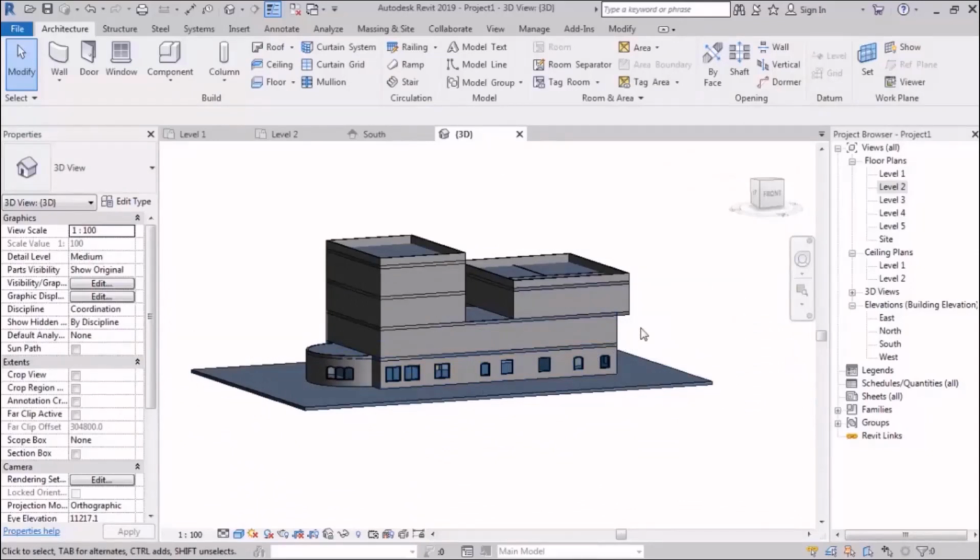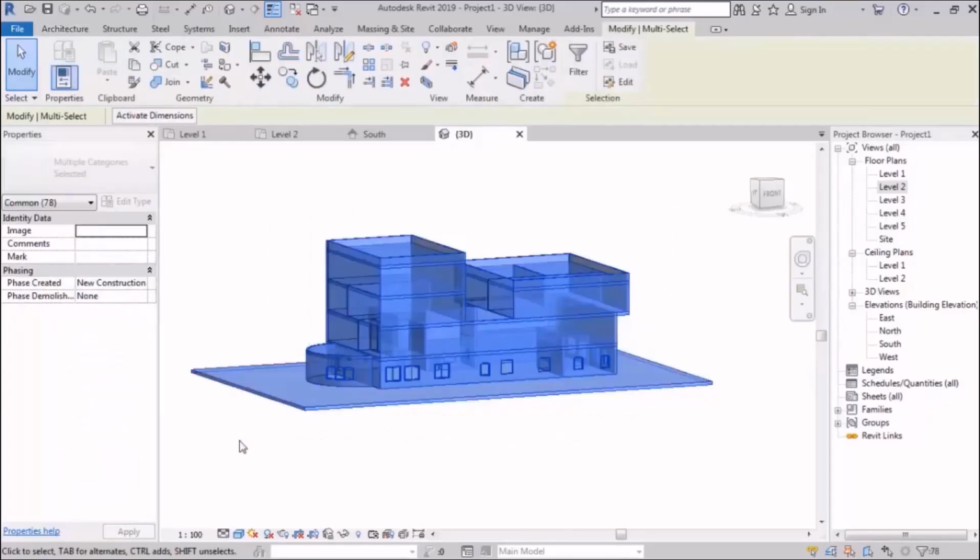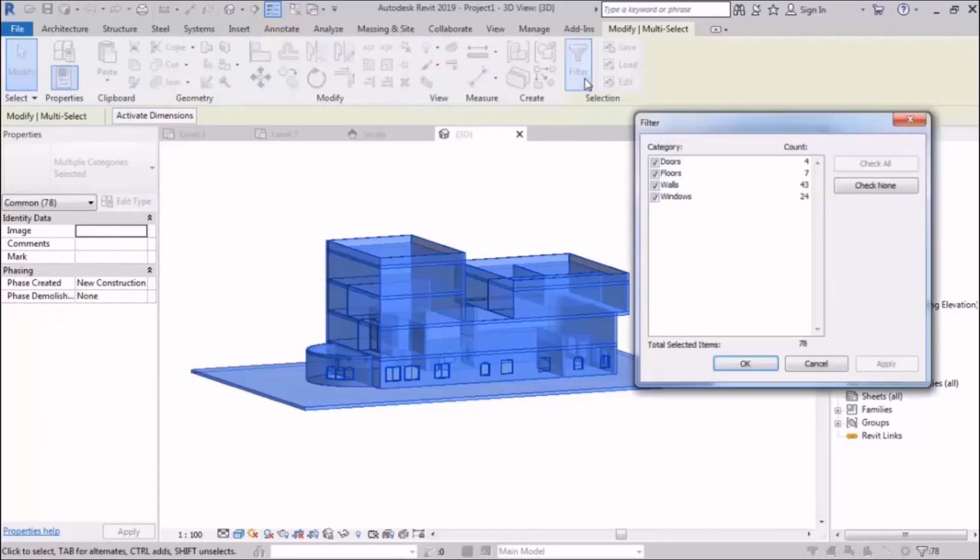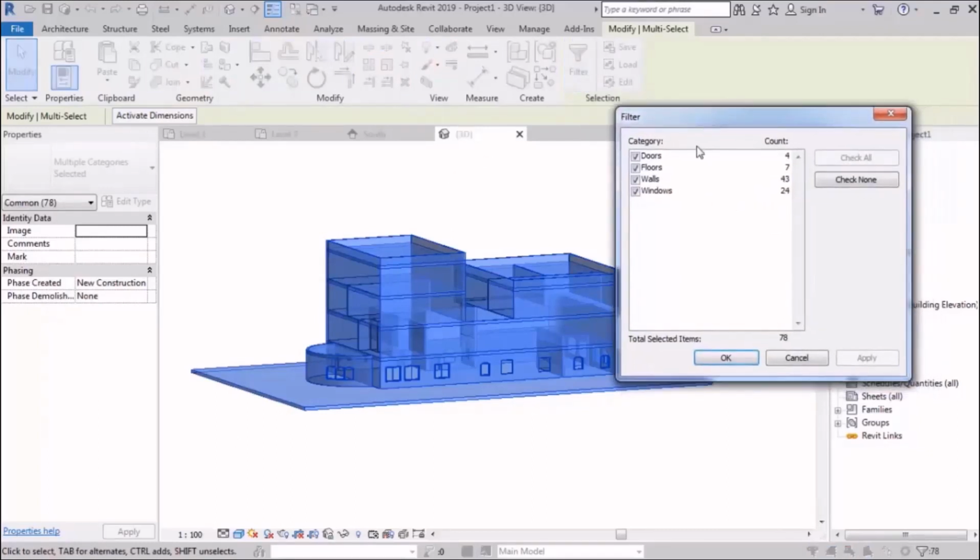There's a technique here that lets you filter your selection, like in AutoCAD, Max, Rhino, and even here. In Revit, if you open a box and in that box there are different objects, it shows a filter up there. If you click on it, you see the different objects in that selection and also the number of each of them.